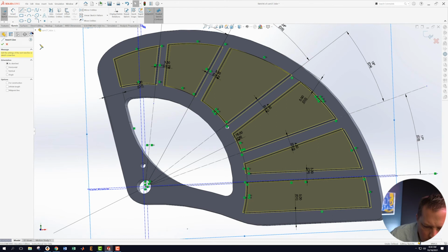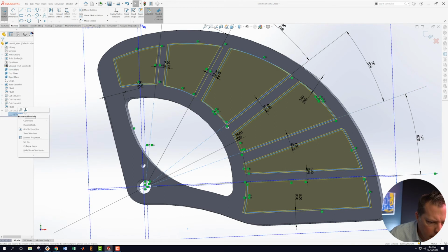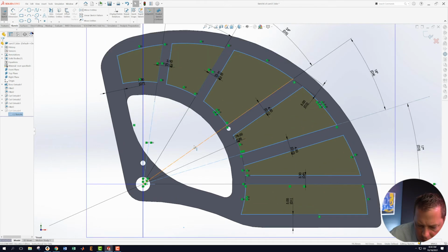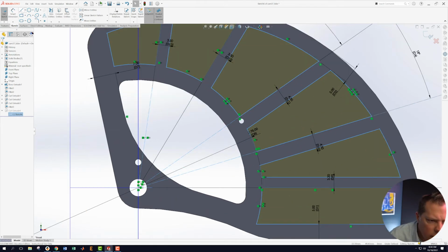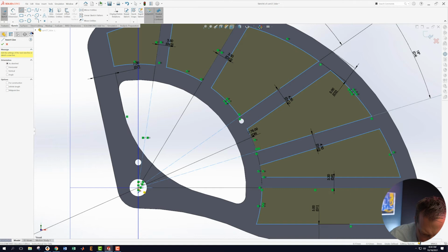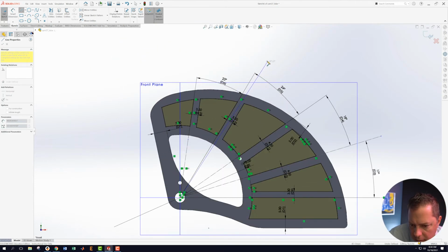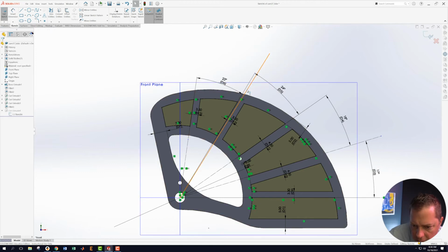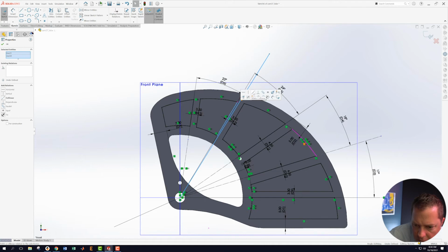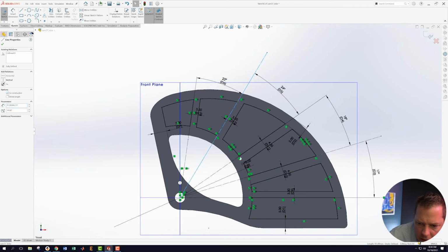So I think our problem is that, let me go back looking at this normal. Okay, it looks like one of my construction lines has disappeared. So I'm going to come over to here. Maybe it's that thing I deleted a while ago when I'm like, what the heck is this thing? Okay, I need this line and this line to be coincident, or let's say collinear with each other. I actually don't even know if I need a construction line here anymore.